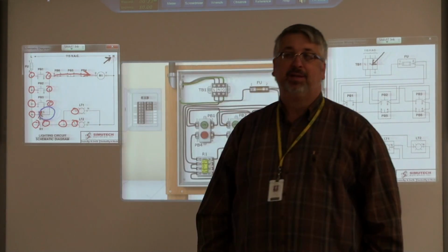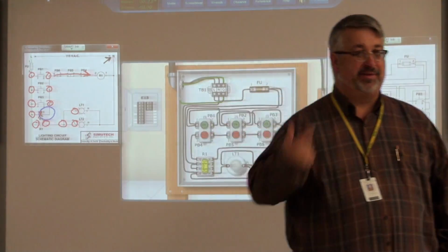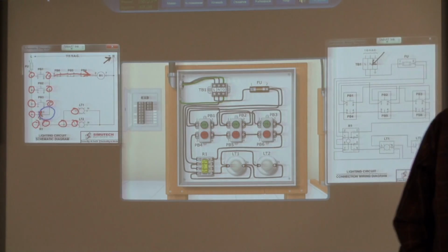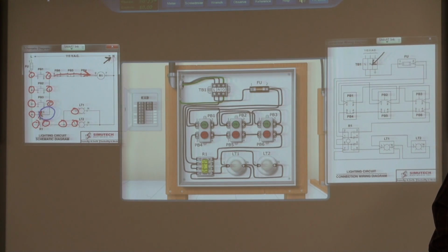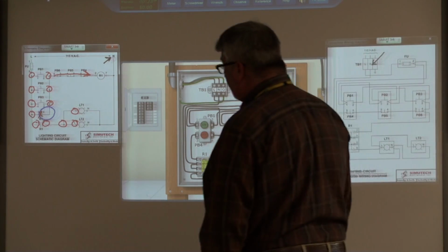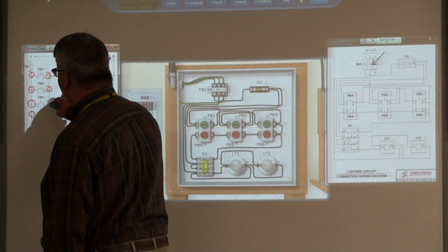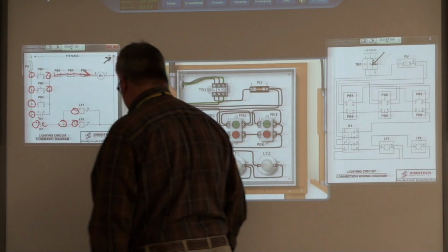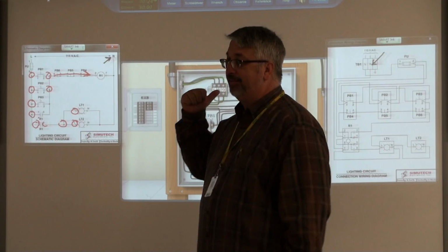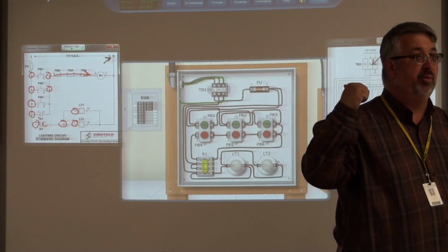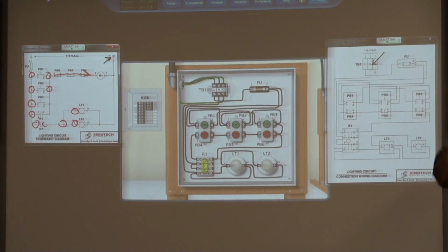As long as you're not pressing, we can trick ourselves. I trick myself into believing that when it's not true. That's one of the things you'll get into troubleshooting that you will do. Yeah, you've got a path there. So you would read that voltage there, but it's not the voltage that's coming through on pin 1 that you're reading, it's the voltage coming across PB1, PB2, and PB3, whichever one you're holding now.